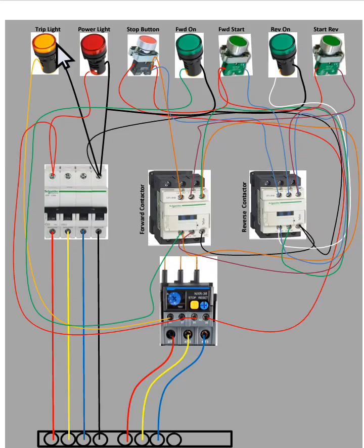When a three-phase motor is supplied with two phases, it tends to draw a very high current. So these are the things that can cause a motor to develop high currents and possibly trip the breaker.